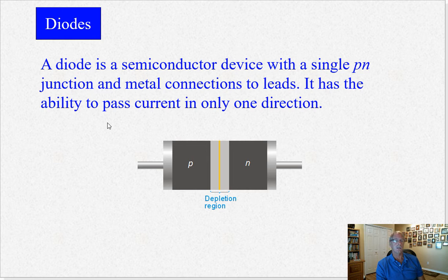They're also used as protection devices on external circuits, things that go to the outside, for example, on connectors on PCs and your phone and so on, to protect against large currents or voltages entering the circuit. They'll block those spikes, if you will. They're all over the place, and there are some special kinds of diodes too that we'll touch on as well. But the most important thing to remember is that a diode is like a one-way valve.